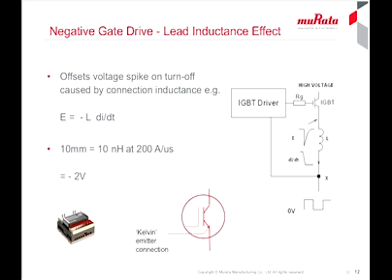Remember from our last slide that a silicon carbide MOSFET can have a switching threshold voltage of just 1.5 volts. Driving the gate to at least 2 volts negative offsets the transient voltage, producing more reliable operation. As an example, the package-induced inductance of a typical IGBT from Vishay, type VS-GB75, is a maximum of 30 nanohenries, which would produce a 6-volt transient under the same conditions.